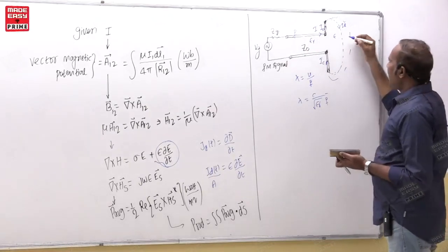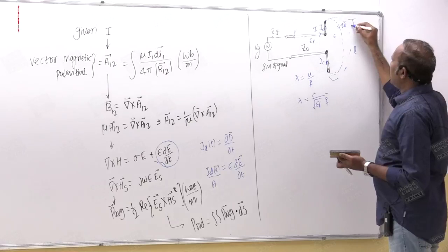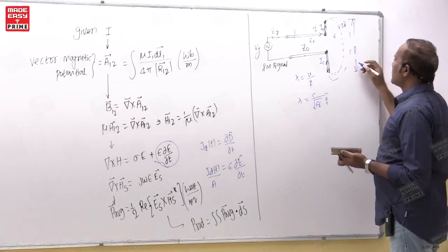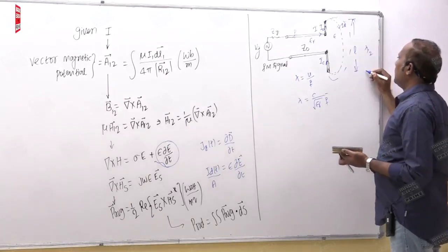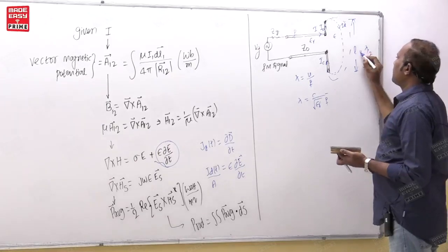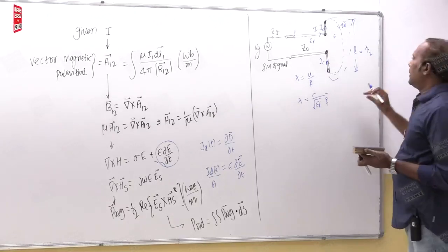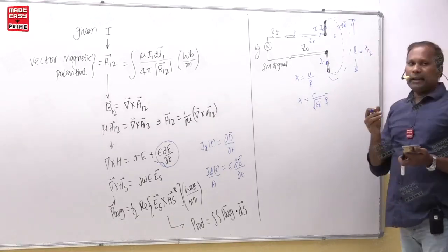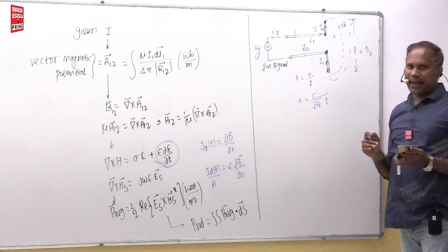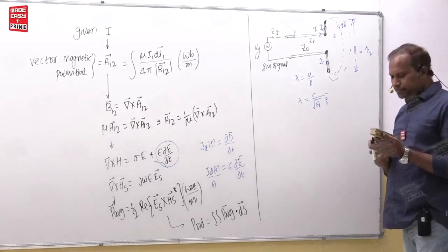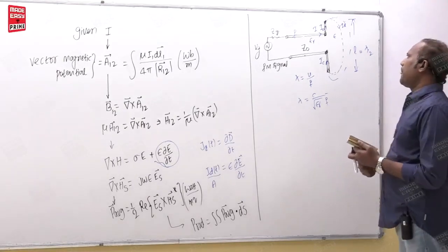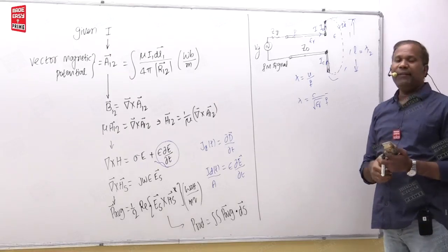Then whenever the physical length of this antenna approaches lambda by 2 wavelength, they observed it starts radiating. That means at this condition, the disturbance in the conductor is very, very high. So dear students, disturbance here means high frequency signal.